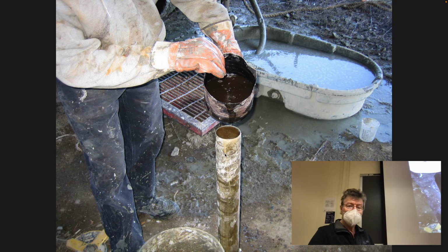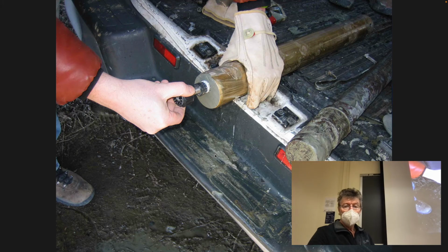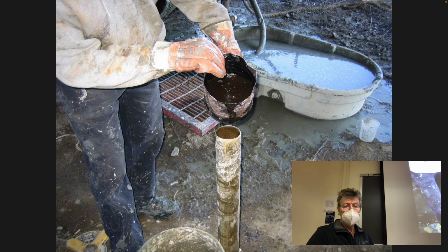And then I mentioned that once you have the samples, you don't retrieve the samples from the tube on site, you merely seal it. So this is paraffin wax melted with a tiger torch, pasted in the open Shelby tube to seal the moisture in. This is the thing that attaches it to the sampling thing. And you'll do this at the top. You'll pull some of this soil off here, so you recede it back maybe a couple of inches, and you'll seal this end as well. So this end and the top end are both sealed with paraffin wax, and you send it off to the lab to do whatever you want to do with it.